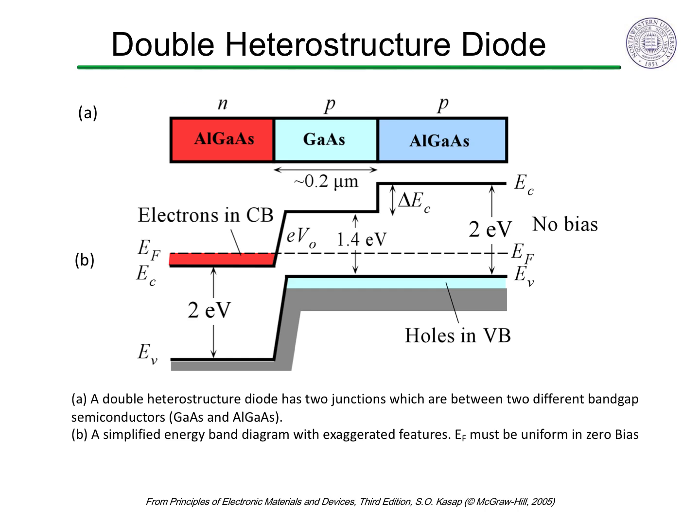The idea is to make a thin film of material with the band gap you want, here 1.4 eV gallium arsenide, called the active layer, in between materials with a larger band gap, here 2 electron volt aluminum gallium arsenide. Again, the structure is a diode with one side p-type doped and the other n-type. The active layer here is lightly p-doped.